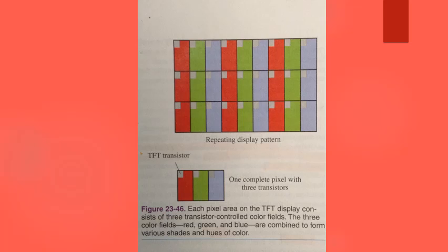The conventional television has used the CRT for display images because the original LCD design had limitations that could not compete with larger display units. As the size of the display unit grew to over 18 inches, problems developed with the brightness of the display and in converting the analog television signal to a digital signal and to a wide-angle viewing area without image distortions. These problems were solved with the introduction of thin film transistor LCD technology.